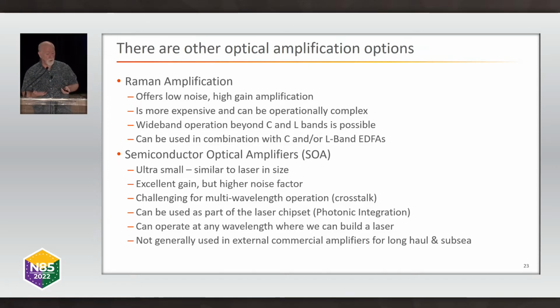There's a technology called SOAs, semiconductor optical amplifiers. They're very, very small. They're similar to a laser in size. They have excellent gain, but they have a higher noise factor than EDFAs. We tend to think of them as being very challenging for multi-wavelength operation.